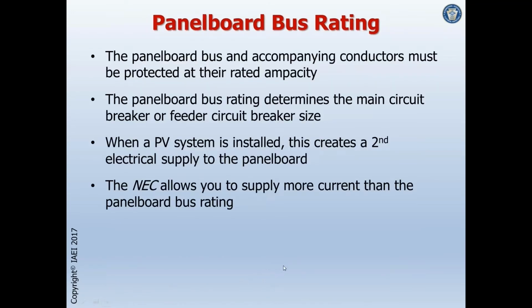And we have to, again, remember that bus bars are conductors, and all conductors must be protected at the rated ampacity. The Panelboard Bus Rating determines the main circuit breaker or feeder circuit breaker size. So what I mean by that is if you have a 100 amp Panelboard bus, can you protect that with a 200 amp main circuit breaker? The answer is no. The basic rule is you have to protect all conductors, including bus, at their rated ampacity.